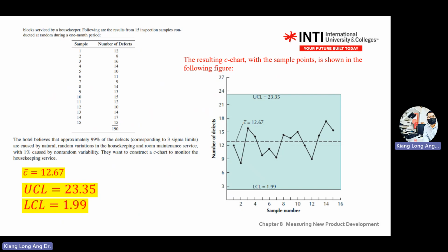If not, then the reject rate. Internally, it means you pass the QA system. However, when it is sent to the customer side and they measure, it's out of spec. So the whole lot will be rejected back. Lot here means one shipment. One shipment may cover 1 million pieces.